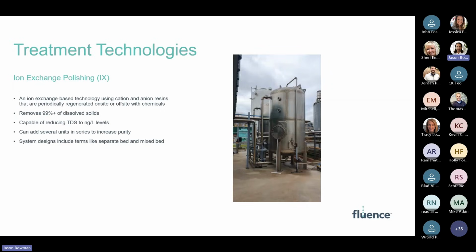for your semiconductor industry. Again, this technology will remove upwards of 99% of the remaining dissolved contaminants from the water and typically produce water with TDS levels in the range of nanogram per liter or parts per trillion range. Like I said, we can run multiple vessels in series to produce the highest water quality possible for your ultra pure needs. One of the biggest downsides of a resin-based ion exchange technology is that they do require potentially hazardous